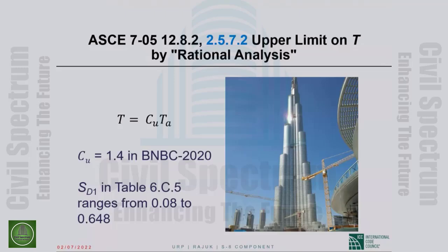and by taking cracked stiffness low enough, you will be in a position to calculate a period as long as you want it to be, which then will give you a design base shear as low as you would like to design for.